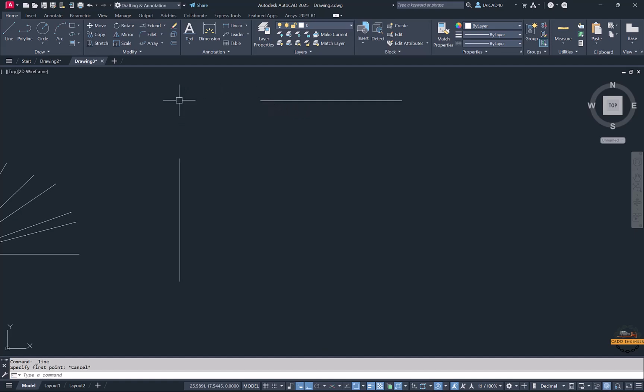Okay, I think it does not become off. Let me turn it off first. Now let's see if you try to track that. Okay, still it's tracking. So if I try to track this point now, it will track endpoints, but it does not track any other points. Like if I try to track the midpoint, it does not track the midpoint. That is the function of this particular part.